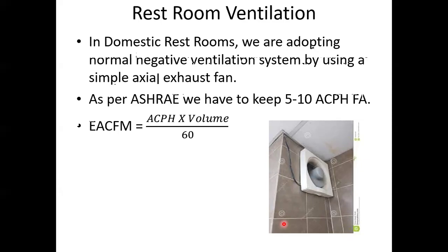Sir, should ACPH always be based on the ASHRAE standard? Exactly, especially for this kind of large area. Normally for office areas, they will consider like 1, 2 something. But for these domestic restrooms, when it comes to negative ventilation, you need to follow those standards itself. What about very large offices? No, it's not meant to be office area. I told you it's for domestic, like apartments and homes. Office area is different. That's what I'm going to say.